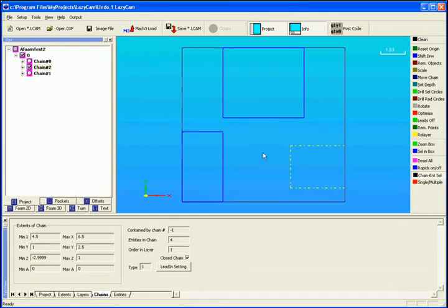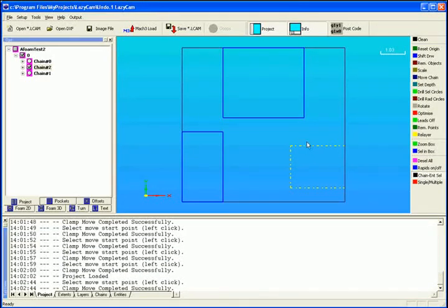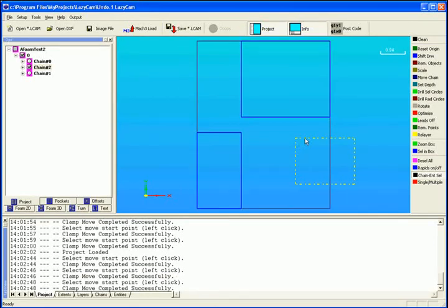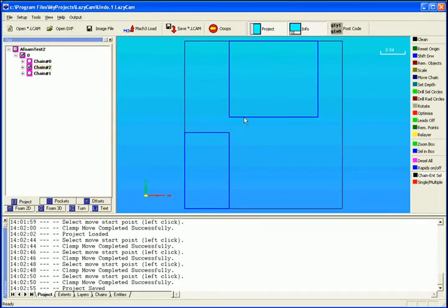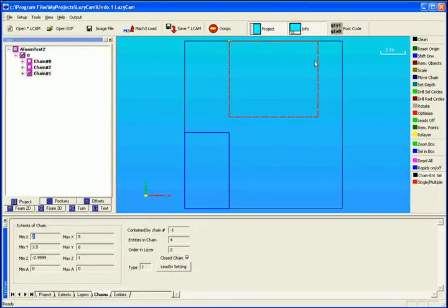And you can see when I did that, the box became a clamp. And it's also in the drawing so that you can use it with any drawing. If we right-click and say Remove Shapes, it goes away. So let's look at this large box we have on the screen and pocket it with a clamp.